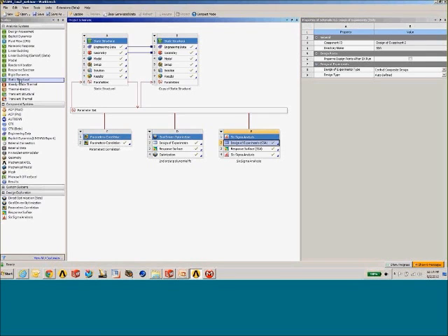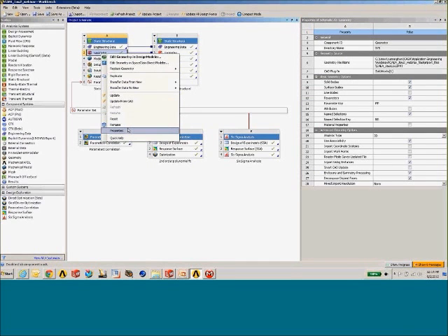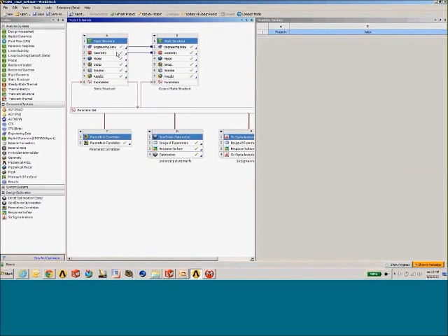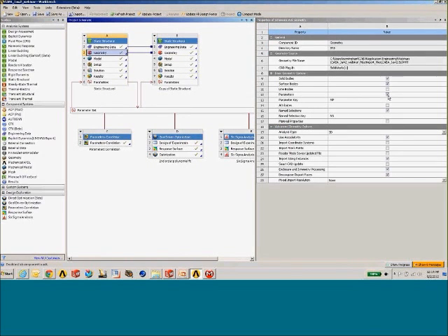So I dragged and dropped a static structural solution onto that geometry, and the first thing that I want to do is tell Ansys to include the parameters in the geometry transfer. I do that by picking on geometry and viewing the properties pane, which is over here on the right. And in the properties of my geometry, I click on the check mark for parameters. So include the parameters, and then additionally use the parameter key that I've specified to filter out the specific parameters that I want to bring across.